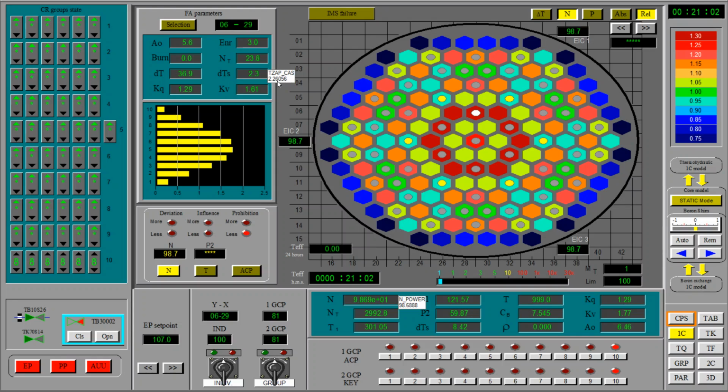Wait, this increasing? Why is this, we have a pressure, the power decreasing now. I will withdraw rods. Okay, we're at 100 point something. 1.8 degrees from boiling. 120 bars in the primary. It's crazily low. And we're at 21 minutes of simulation.